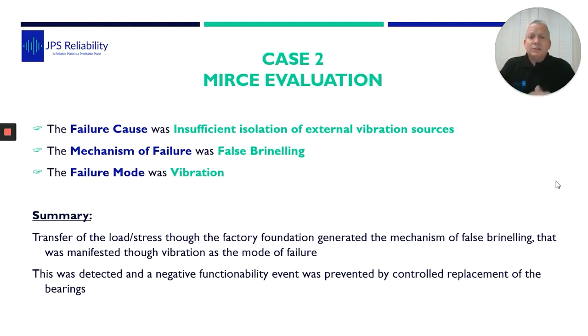Looking at the whole system, how it's set up, we can say, bringing the science into it, that the failure cause was insufficient isolation of external vibration sources. You can say something about the lubrication being contaminated or poor, but even if it's contaminated and poor, if there was no vibration, this would not cause the false brinelling. The mechanism of failure was false brinelling, and the mode of detection, the failure mode, was through vibration. You can put in audible noise as well, because obviously they heard it too.